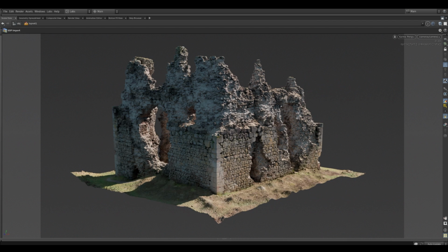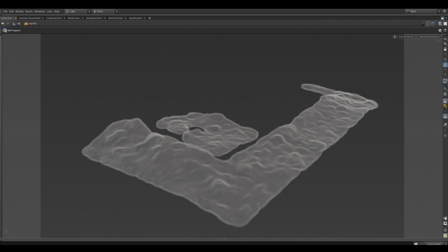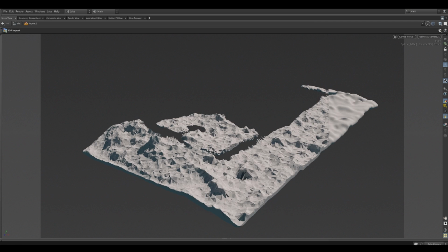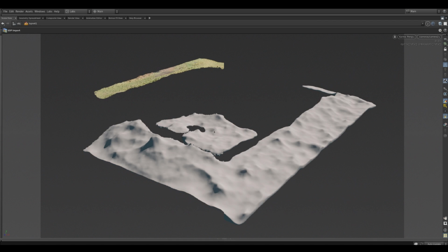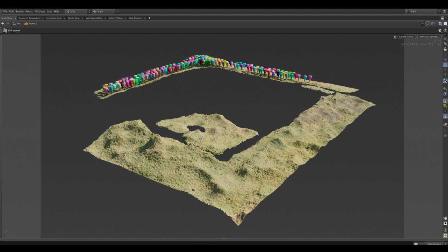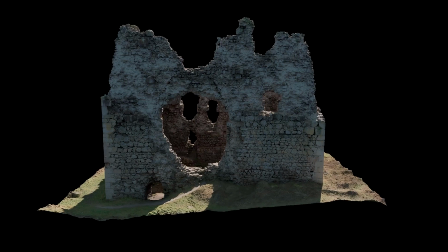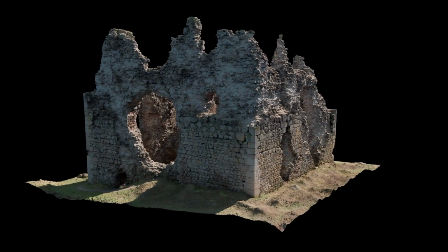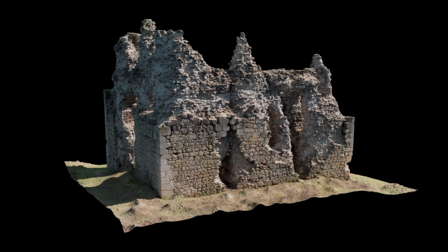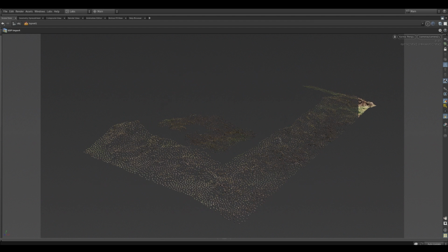We first turn the terrible geometry into a point cloud and use metaball to scatter onto the point cloud. That'll create a smooth merged geometry. Then we convert that smoothed out geometry into a VDB volume. Then we can further smooth it. Then the VDB volume will be converted back into geometry. Once we get to that step, I'll pause here.